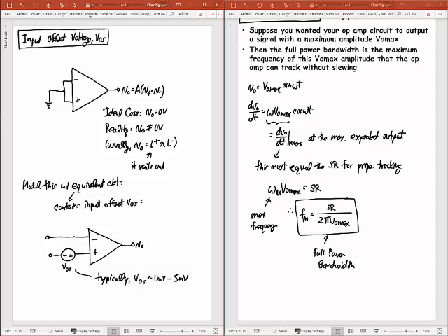But if you take 1 millivolt times the gain of this op amp, what's the gain of the op amp in your lab? You may not have determined yet. It's going to be pretty high. Okay, but take 1 millivolt, multiply that by 50,000. What's that going to be? By 100,000, right? That will rail out your op amp. Okay? Maybe it won't, depending on the gain of your op amp, but a lot of times it'll rail it out. So you can run this experiment in the lab. So that's one practical difficulty you have with this V offset, that when you put 0 volts between plus and minus terminals, your output is not 0 volts, it rails out.